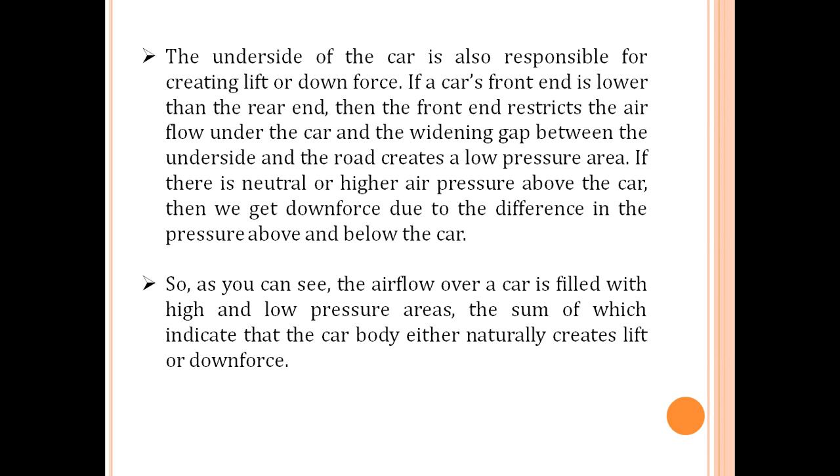When the front end of the vehicle is lower than the rear end, the front end restricts the airflow under the car, and the widening gap between the underside and the road creates a low pressure area. Because the front end is lower than the rear end, it restricts the airflow.